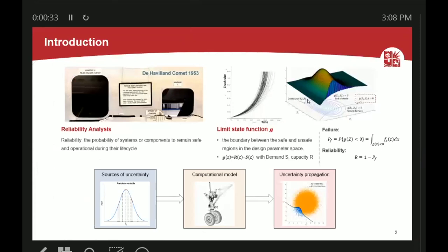Right. Look back into the history. The de Havilland disaster is probably the most iconic accident that leads to our modern consideration of crack propagation. The fundamental cause of this accident is basically a crack initiating from a rivet hole and propagating through the pressurized cycles. That means that we need failure analysis and robust fatigue testing before certification.